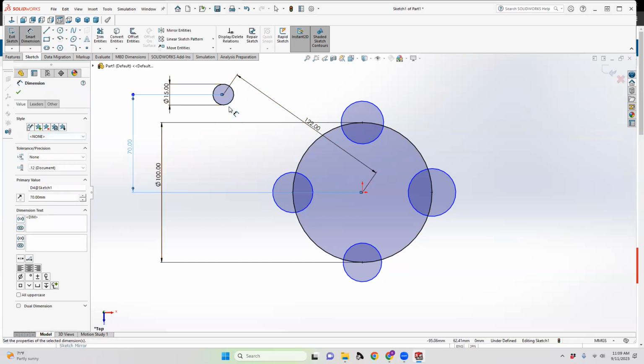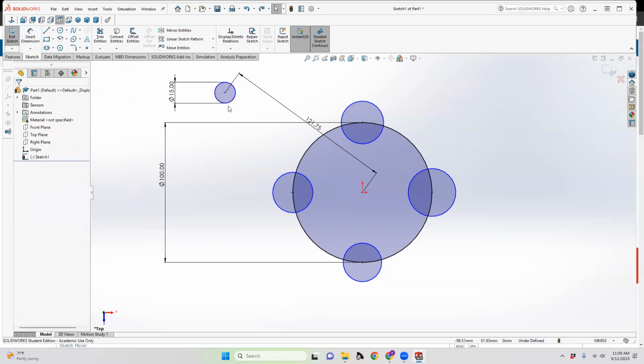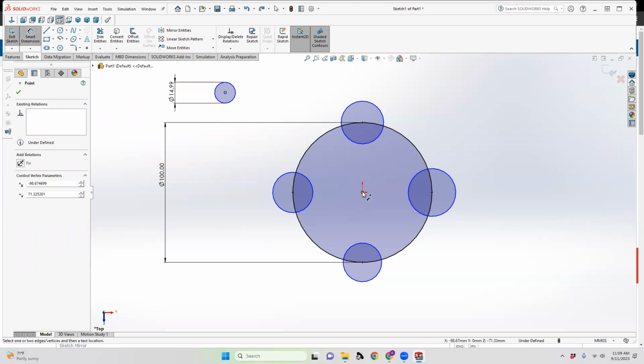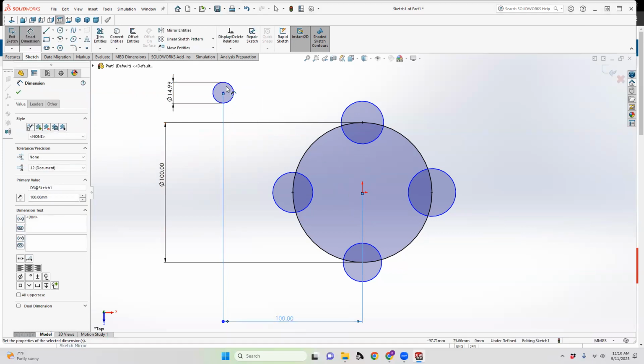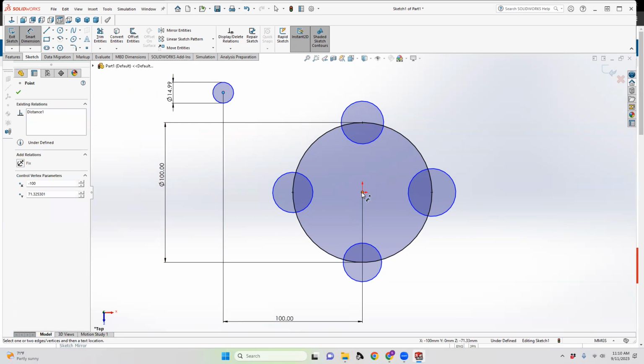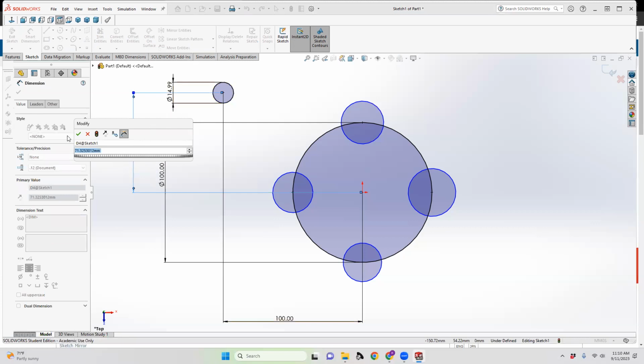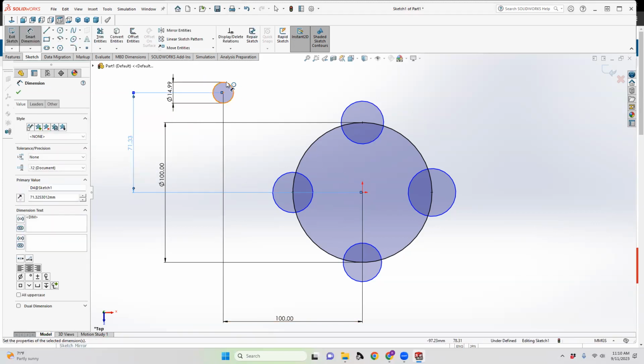So you can get there this way, or you can get there by what I recommend, especially for a thing later on that's a horror story that you guys may or may not have heard, called the French curve. You want to try and reference the origin whenever you can, or something that's adjacent to the origin. So if you reference the origin for X and Y and then set one other dimension, you're almost always going to get full definition for something. And that's what's going to give you the information that you need.